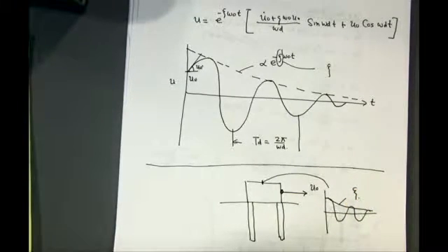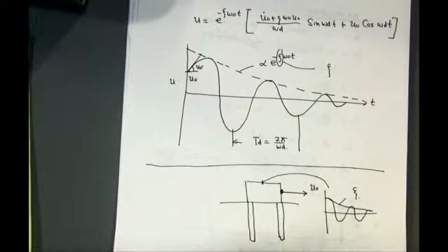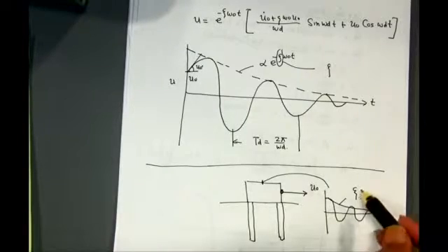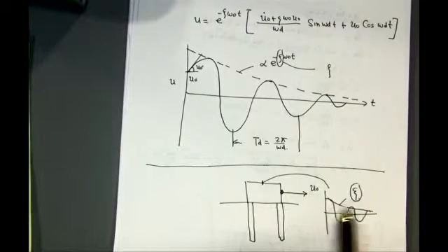This was very useful, and this has been done on real projects. In fact, in some cases entire earth dams have been pulled and allowed to vibrate to calculate the damping property of the material. Okay. Now this is the case where we have systems freely vibrating.